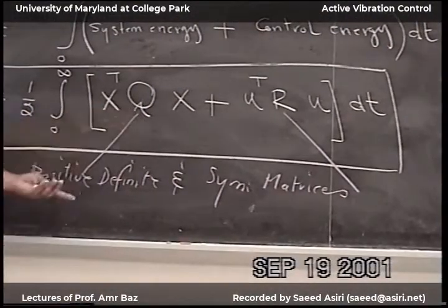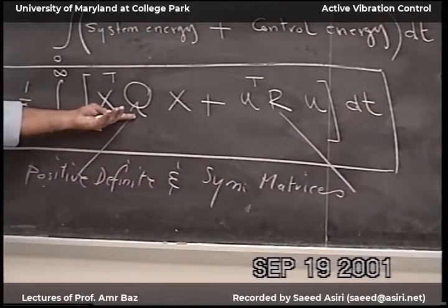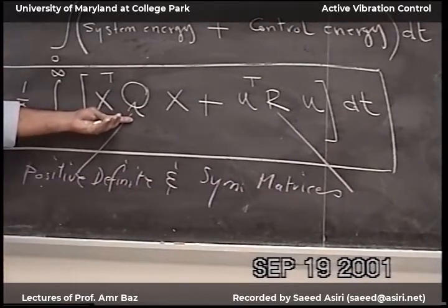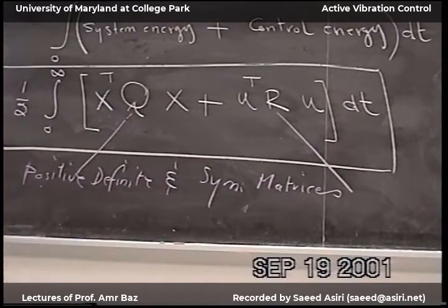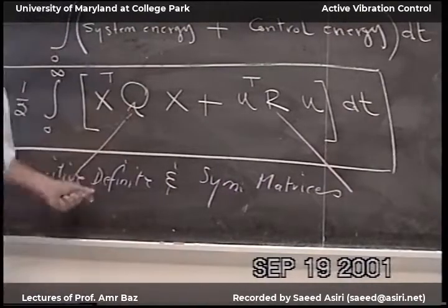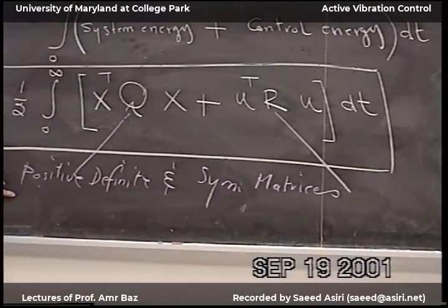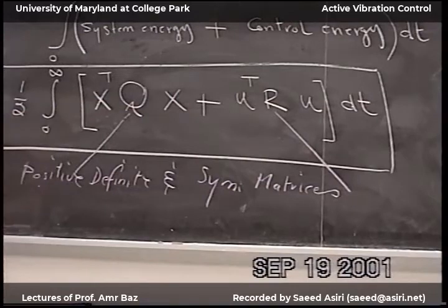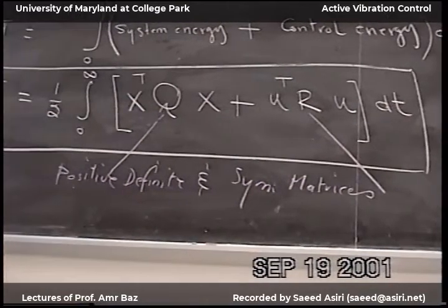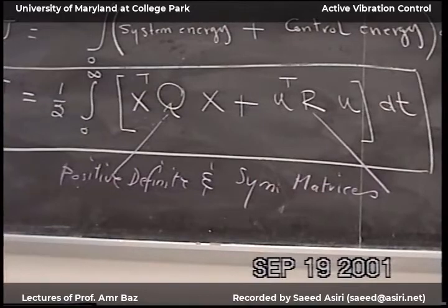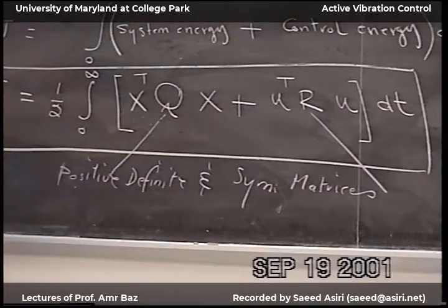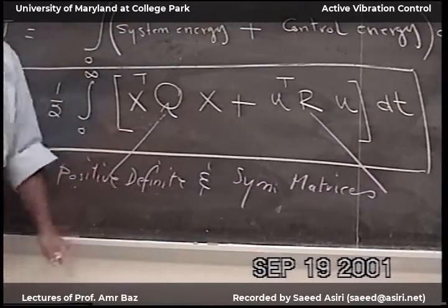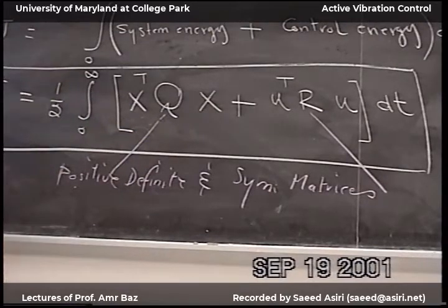The reason for this to be positive definite: it has a mass matrix, for example, and a stiffness matrix. Both of them are positive matrices. And again, both of them, for any structure that we are selecting, have symmetry. Okay. Rob, does that also imply that it has a minimum? Like it's concave up? Yes, sir. This automatically will give you one single minimum. This objective function has one single minimum. So this makes the quadratic optimization very nice, and we'll have one single solution.